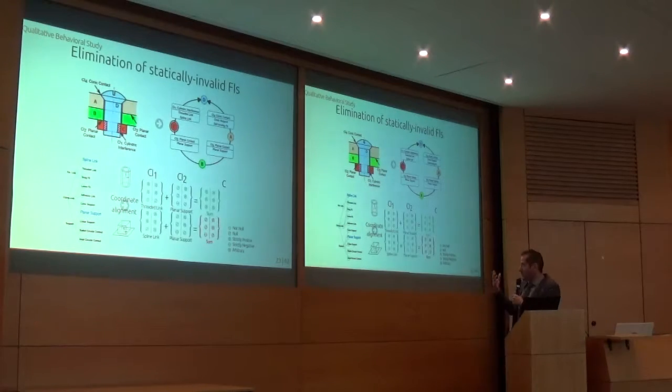Now, the other alternative, which is the solution of a spline link and a planar support, however, has a strictly negative qualitative value that doesn't contain 0, and this makes this solution rejected. That would mean that the spline link is not an acceptable functional interface, and it is then dropped from the interpretation.